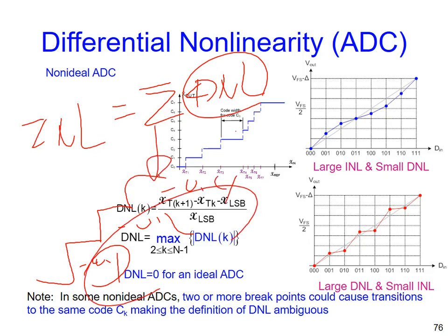So to this step, how to measure INL? I told you already, you need to sum up all those. The first stair, the second stair, the third stair, all the way to here, right? So if each stair becomes smaller than the ideal value, they all get negative DNL. So the summation will have a big impact on you. Okay, that's it. That is the very easy concept.